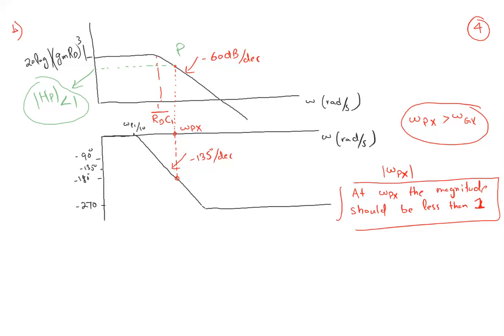Also go through example 12.38 if not clear, but make sure this point is clear because that is very important. So we know qualitatively, if we set this condition, we can find out. So now let's put it in and conclude how it's going to be when we figure it out. So we know our H of s or H of j omega is equal to the DC gain, GM RD whole cube, divided by what is the thing?